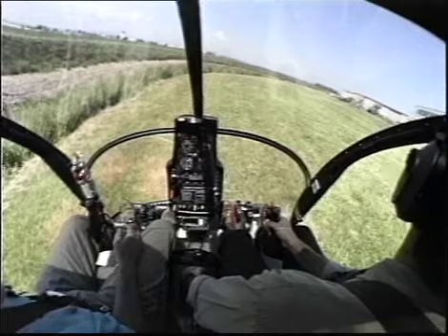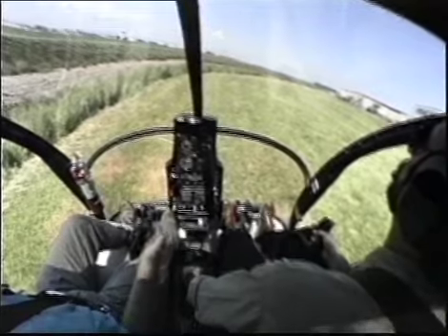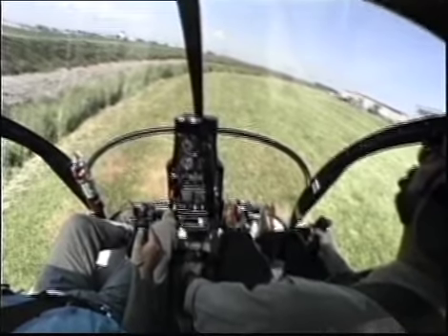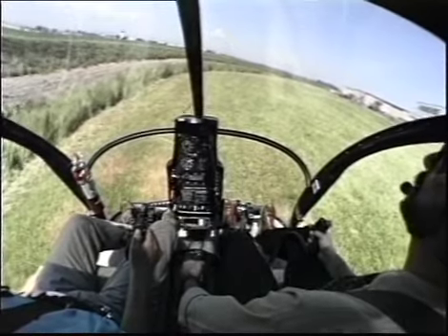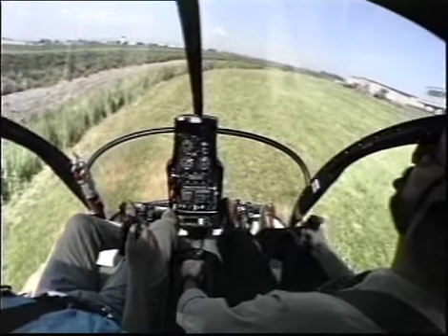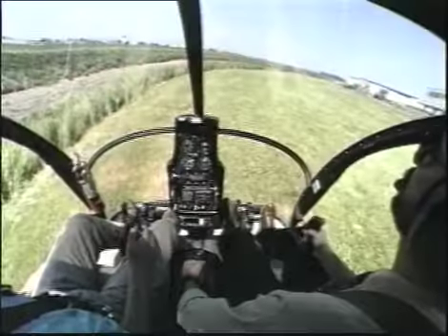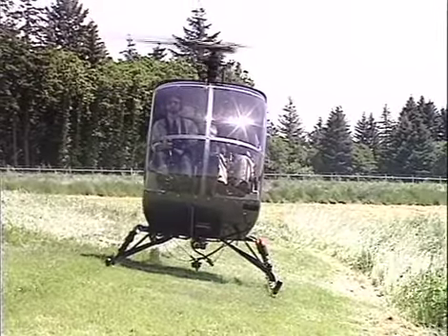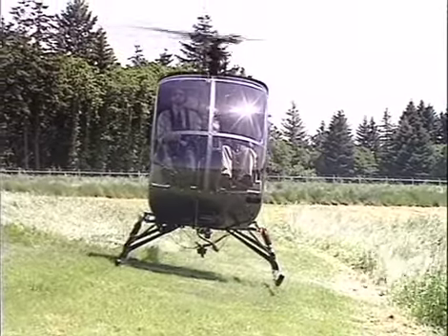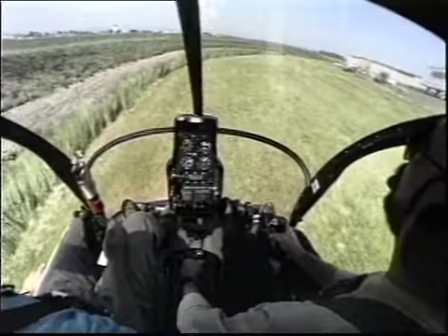Takeoff from a slope is basically the reverse of a landing. Check that the RPM is in the normal range, then move the cyclic away from neutral and into the slope so that the rotor disc is parallel with the natural horizon. Slowly raise the collective so that the downslope skid begins to rise. As you do so, coordinate cyclic movement back towards neutral, keeping the rotor disc parallel to the horizon. Bring the helicopter to a level attitude before completely leaving the ground.